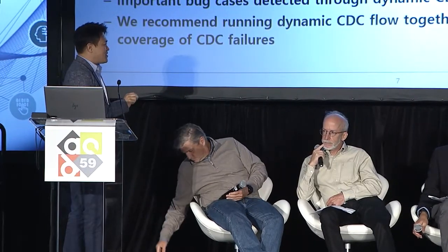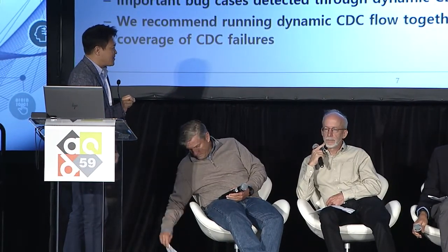How long does it take to run this tool? When you run static, it's usually fairly quick, and dynamic is usually slow. How long does it take to run the dynamic CDC? I think maybe 15 to 20 times simulation overhead. But again, the key is achieving good coverage.